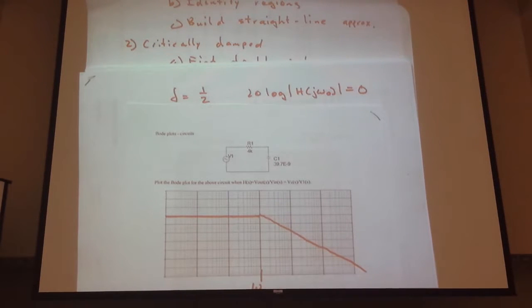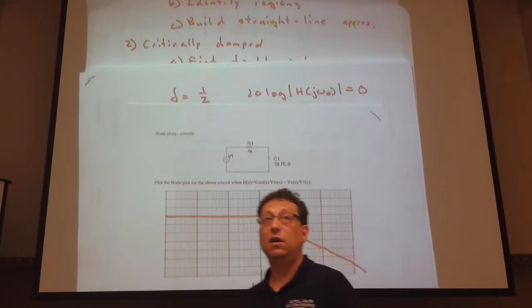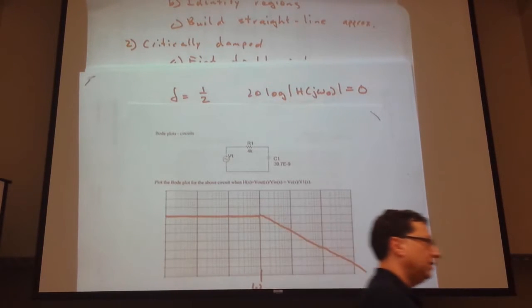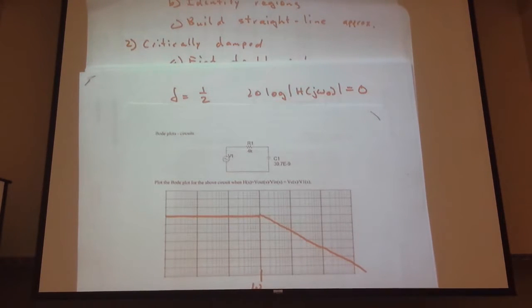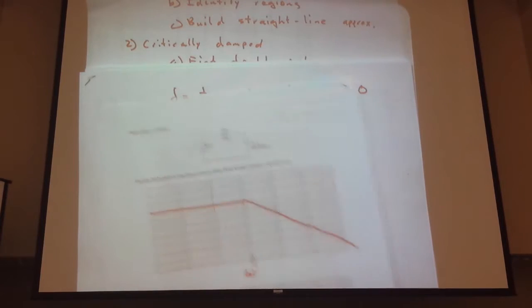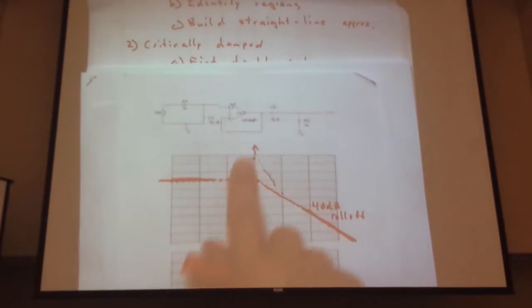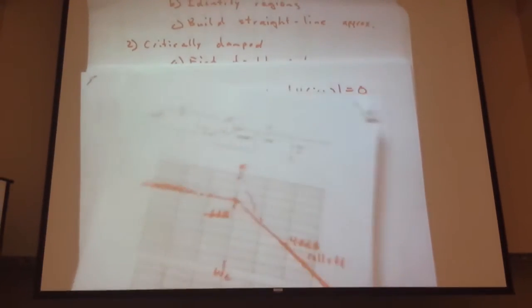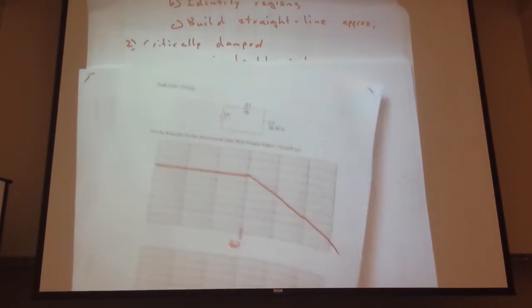So the second order circuit would give us 0 dB relative to the passband, but the first order circuit that we also need to give us the triple pole, -3 dB. So we would add things there. So this slope kind of tells you information about what's going on at this corner, this cutoff frequency. And again, you can underdamp more, but then things start to get a little bit ugly and you stop building a real good filter there.